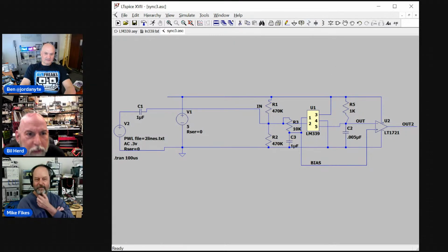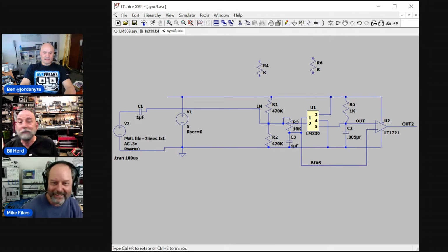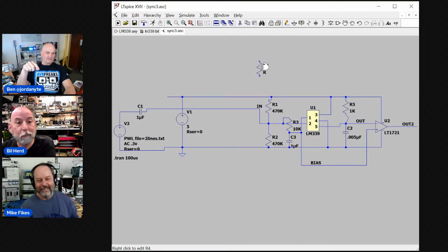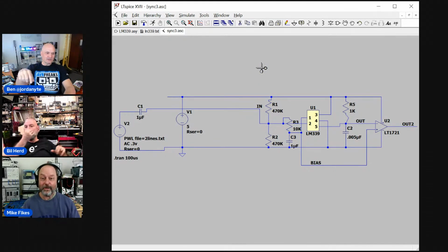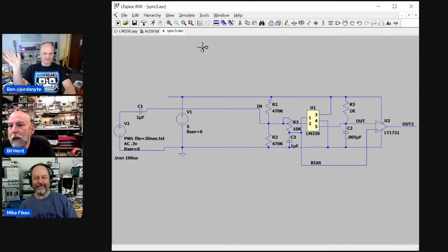You can, let me get my mouse in the right screen here. But also, Bill, you were able to give it to me. Yeah, I don't have Altium. Anyone can do this. There's another trick. Mike, I can generate something in Altium and send it to you, and you can run it in LT. Nice. Because I can just send you the Spice netlist, which means you don't require the actual binary schematics or anything. Yeah.